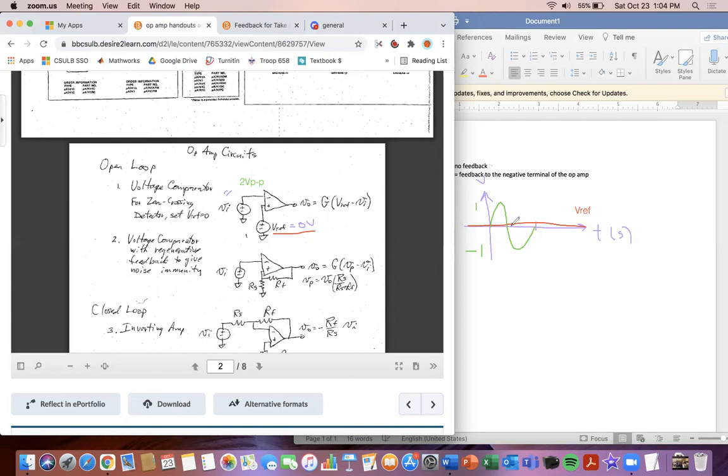And we're going to see V reference. We have a zero crossing detector here because right here at the 0 point, and here at the 0 point, and then right here, it's going to cross. You can see the two intersect, and at the point where they intersect, there's going to be a change in the output voltage. When V reference is greater than VI, I'm going to do a little equation here: V reference is greater than VI, we get a positive number on this side of the equation. But if V reference is less than VI, so if VI is bigger than V reference, then we get a negative number. That's how you look at this side of the equation, and the output will be reflective of that change.